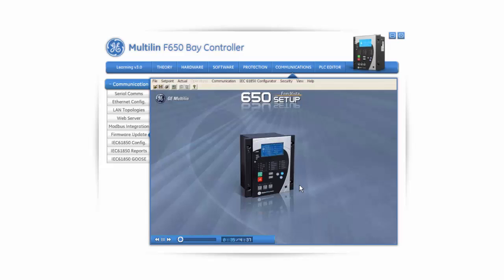The firmware upgrading process is completed using the EnerVista 650 setup software with an Ethernet connection, COM3, via crossover RJ45 Ethernet cable. Firmware Upgrade. We shall now learn how to upgrade the firmware in our F650 relay. We shall do this by downloading the new firmware file from our PC to the relay.